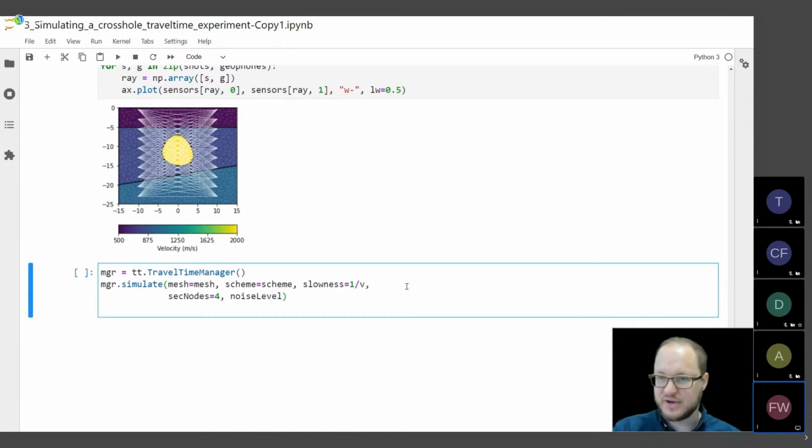I'm specifying a noise level, which would be 0.1%, and we usually define the noise for travel time measurements in absolute terms. Could be a triggering offset, for example. This would be in the same units as we have the data, so in seconds. And then we can also provide the NumPy seed to create the Gaussian distributed noise so that we have this reproducible for our research work.